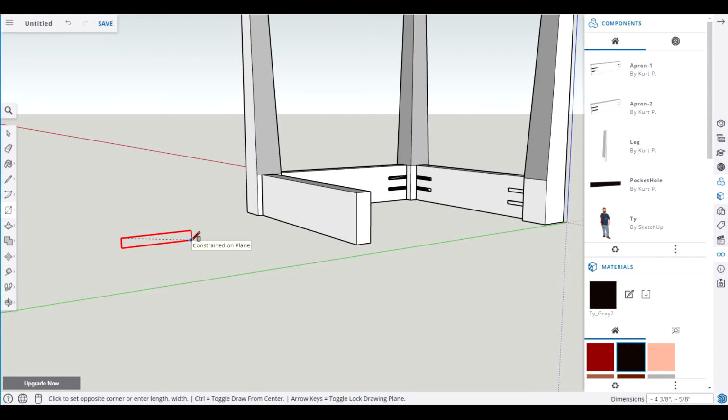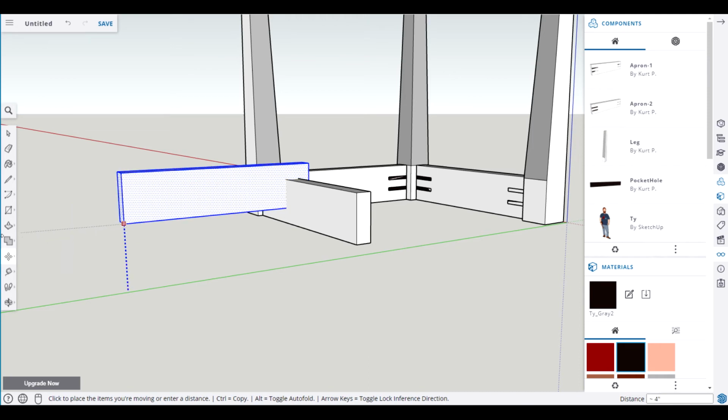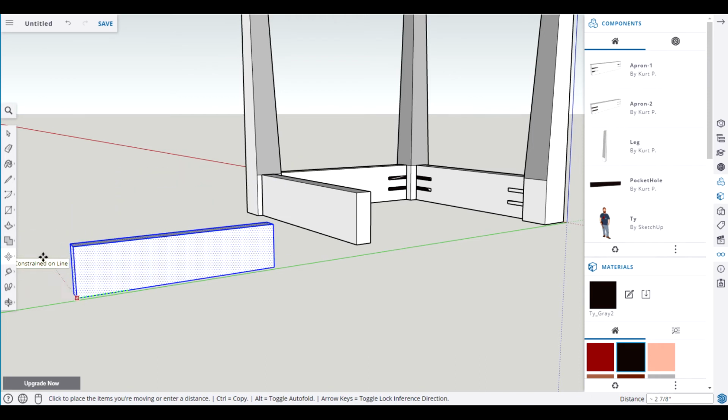As we can see now in this case here, the length is going to be 12.75 is the first dimension. That's 123. We don't want that. 0.75, comma, 3, enter, space bar, P, click for push pull, drag it, 1, space bar. Let's triple click this and hit M, and let's just move it out of the way here so we can go up. Hit the blue key, brings it up a little bit, and then that key brings it down. So we're good. We'll leave it right there on the green.